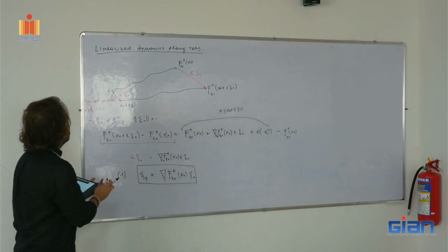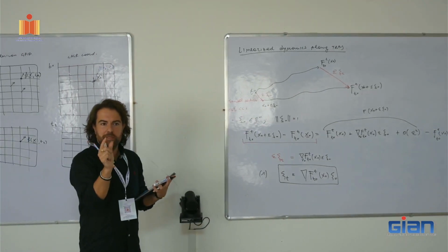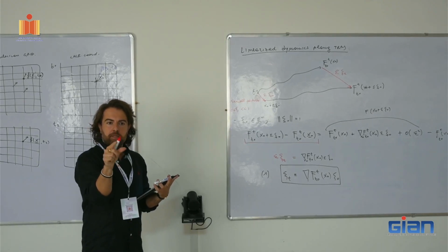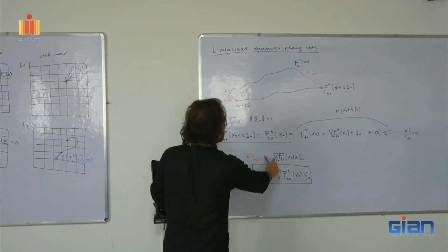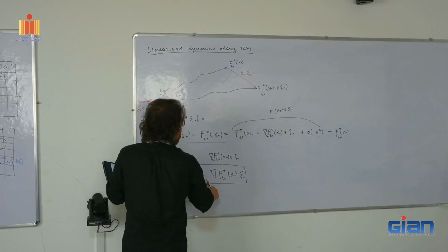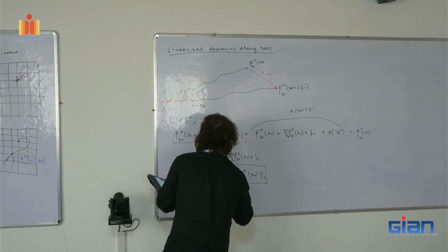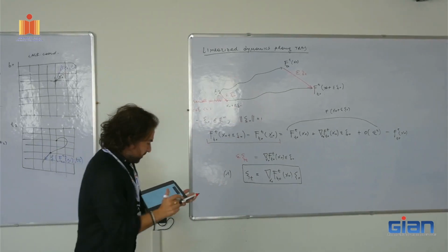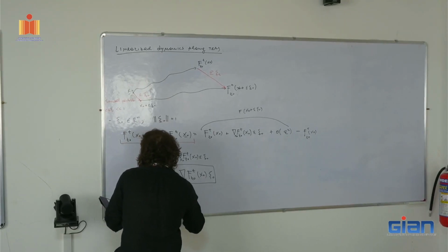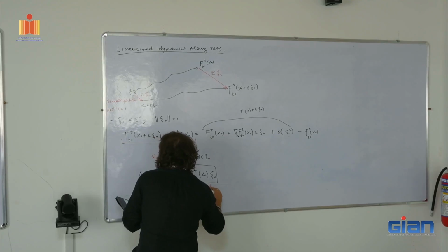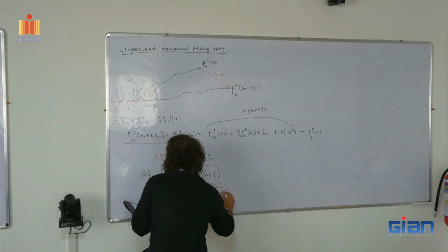So we can think of this perturbation as a material fiber. Think about a little piece of material, this initial segment, that is going to be stretched, transported, deformed by the flow, and this is how it evolves. So at a later time, it is governed by the Jacobian of the flow map, the derivative of trajectories with respect to initial condition, times your initial perturbation. So this is perturbation evolution over a finite time, t0 t.